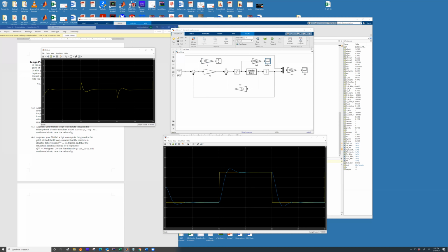So what this tells me is this. Initially, my aileron was at 0 degrees, but I sent a command input. Command input is in yellow. And my roll autopilot managed my actual roll deflection to be about the same as the commanded input. During the step, it kind of lagged behind, but finally it caught up, then went back and it caught up. I want you to run this and see that your actual output in blue is similar to the commanded input.